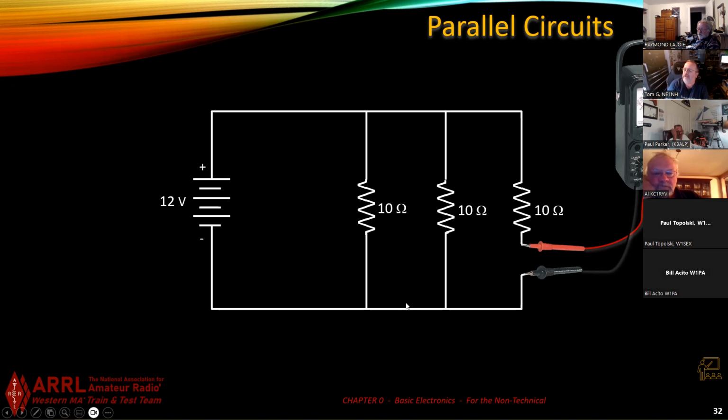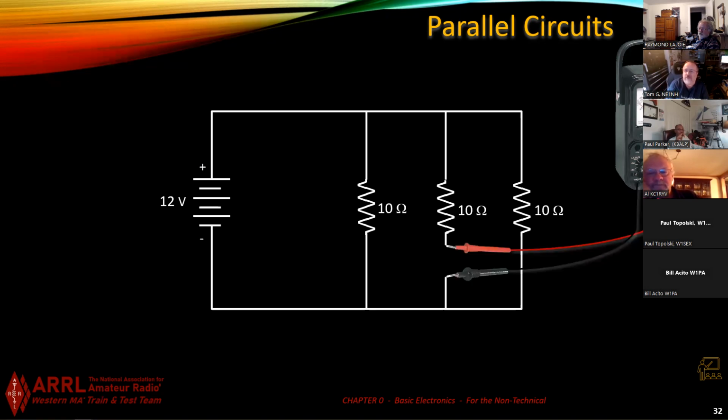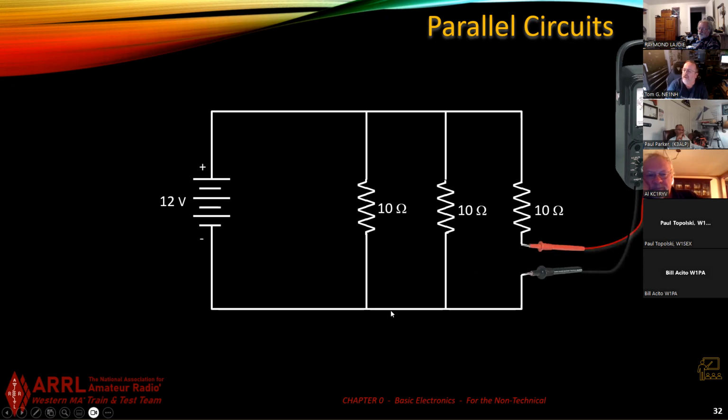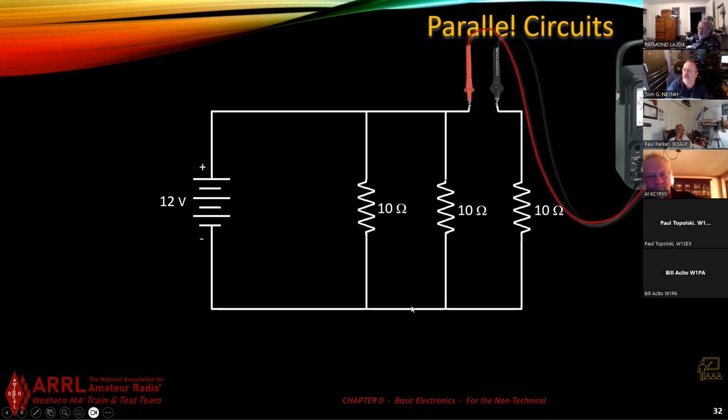So the flow between these two right in here, you mean? No, right between the next resistor on the next branch. Right here? No, behind it. Yeah, that right there. It'll be about 1/3 because it's an equal resistance value. So that wouldn't be 2/3. Nope. It'd be 2/3 down here if I measured right here. Because you got 1/3 of the current going up this way, therefore 2/3 of it is headed this way. So if I broke my circuit right here, I'd measure about 2/3, okay?